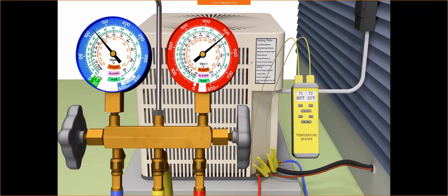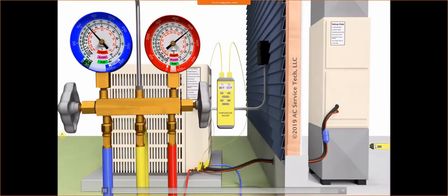That would mean your subcooling is 55 degrees, because subcooling is the saturated temperature on the red high side gauge minus the actual temperature on the small liquid line. If you have a very high subcooling like 55 degrees, you may have that liquid line restriction problem. It could be a clog at the filter dryer, it could be a clog in the screen prior to...